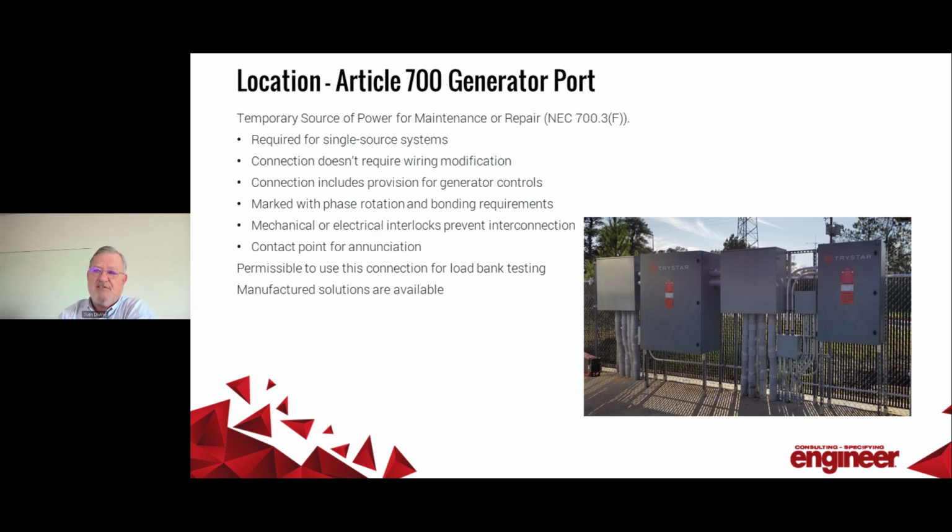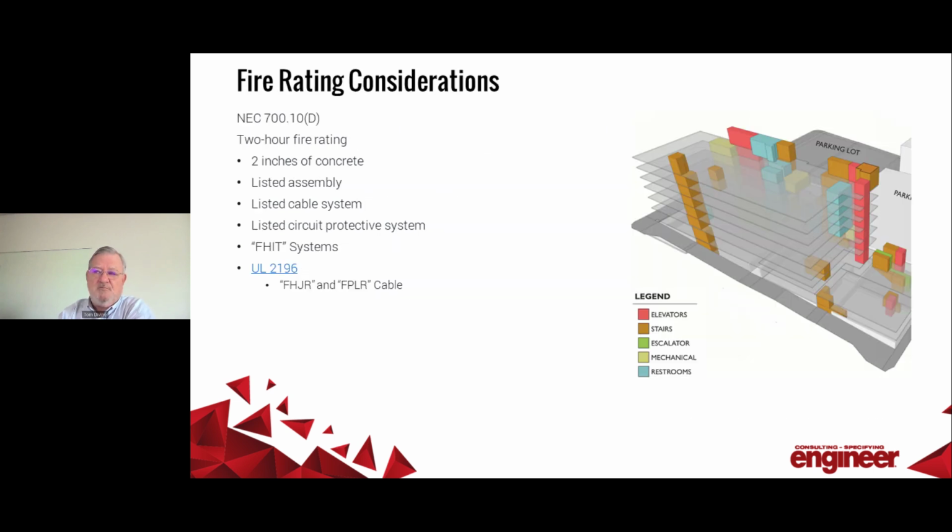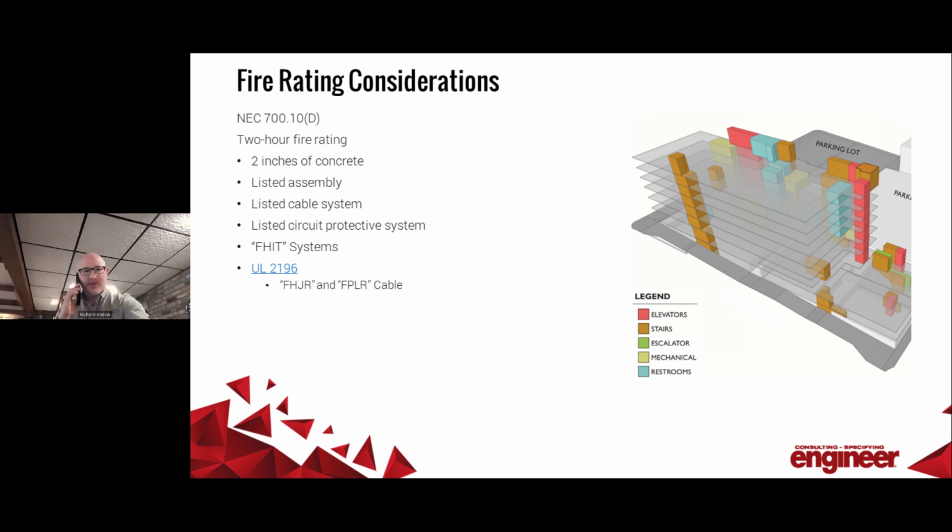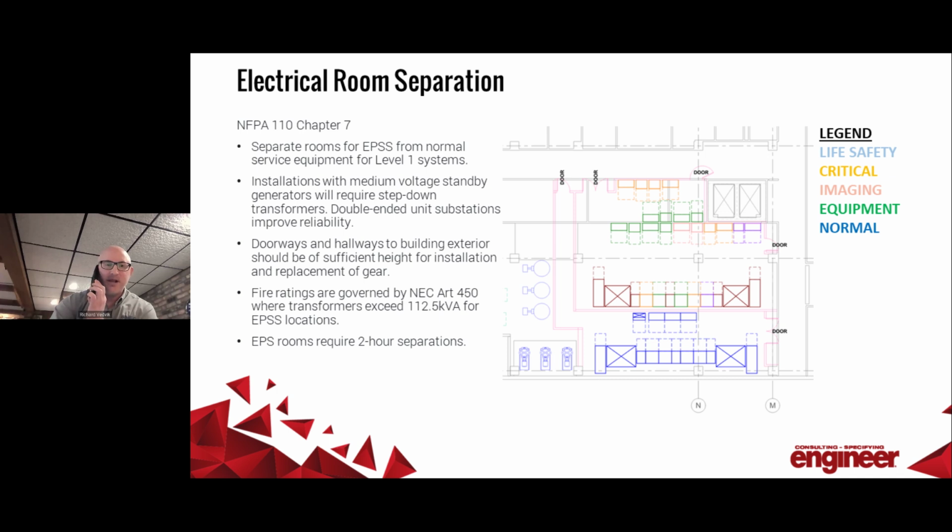Now, Tom had talked about the fire protection sizing criteria earlier, but we want to at least touch on a couple more things, and that is fire service elevators. They're going to have different requirements that you're going to have to coordinate with your fire department, and obviously the fire rated conductors in Article 695 for your fire pump are going to have separate requirements as well. Take both of those into consideration when you're doing your rating determinations.